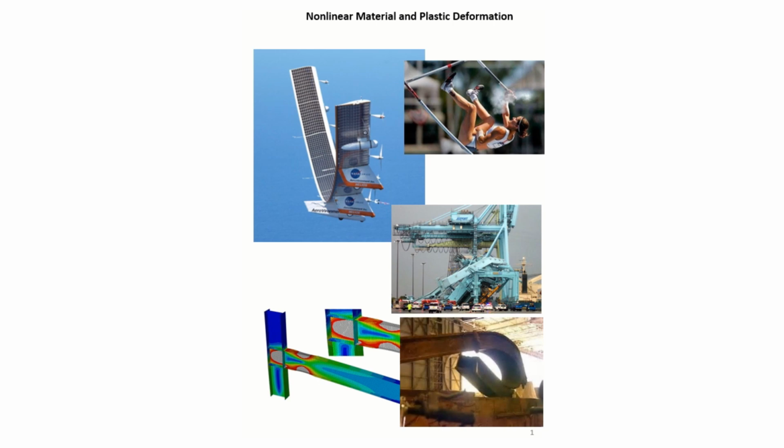some portion or some amount of plastic deformation in the design because it significantly reduces the size of the members that are needed. And so that's what we're going to focus on in this section: learning how to design by allowing desired amounts of plastic deformation. And we're going to look at the models that we use and the theory that we follow to come up with these equations and do this analysis.